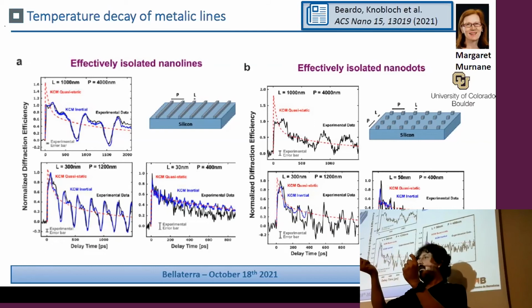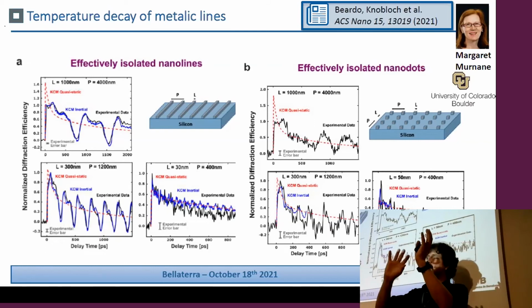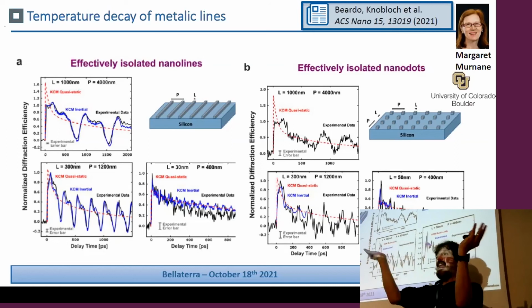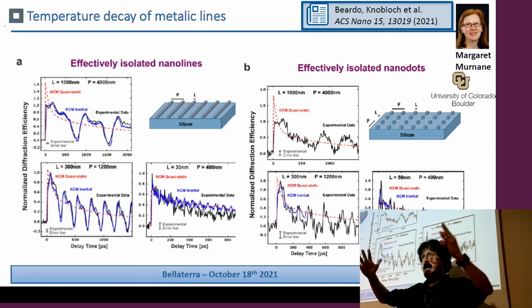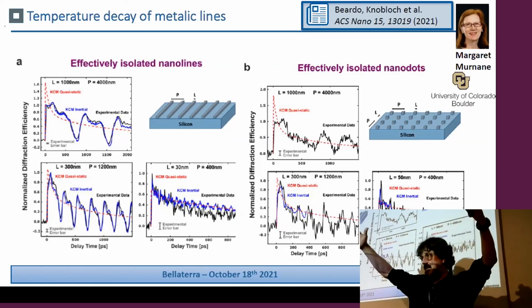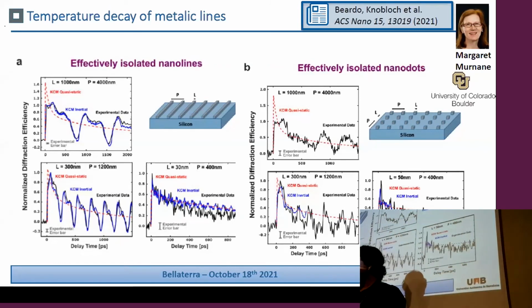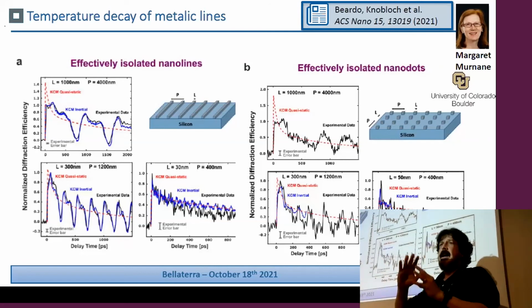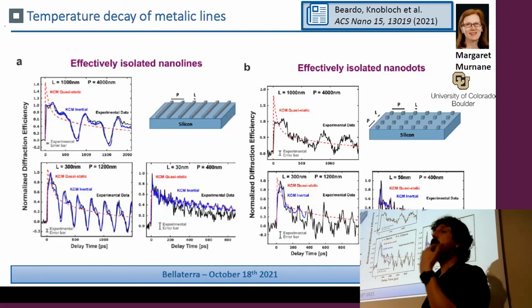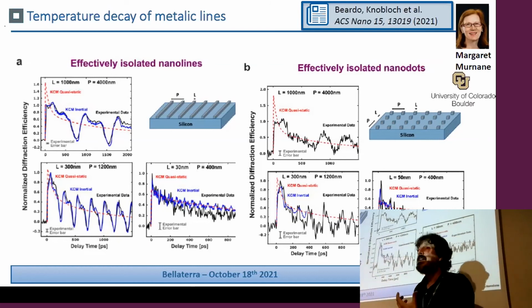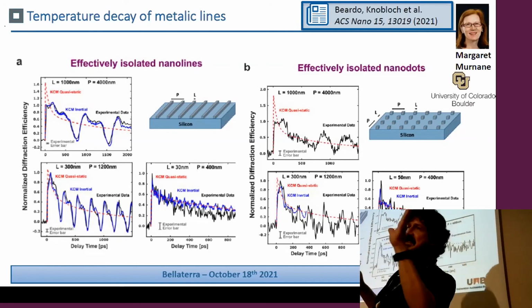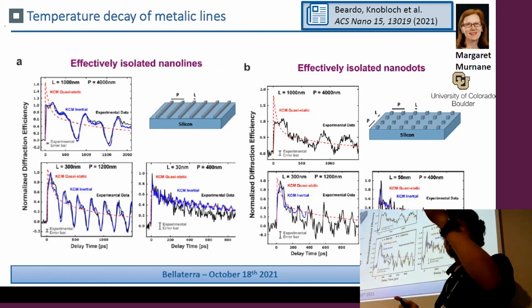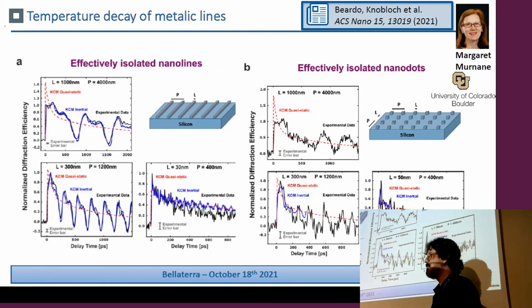And it has a couple of physics. So they have the coupling of the elastic waves and the thermal relaxation. The thermal relaxation gives you an expansion that is decaying because the heat is released. So you can have both physics. The important thing of our model is that we can do it with COMSOL. So we can combine it with the elastic module, and you can heat the plane. That is something that you should do with caution, as Luciano said in the previous presentation.